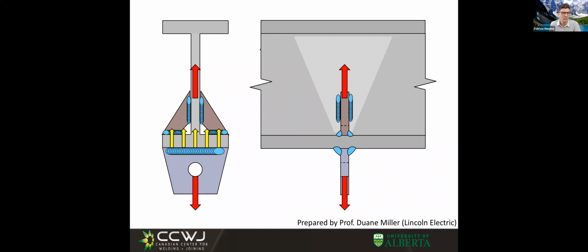We could even do this kind of rocket ship configuration, and that would be okay, right? We are having some kind of a buttress transferring the load. And the load is distributed now, the stresses, we don't have the stress concentration in the center anymore, because everything is equally stiff, right? Very, very interesting.